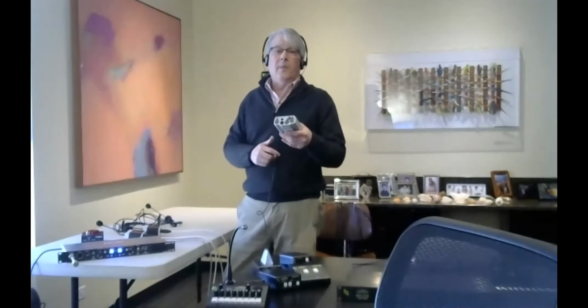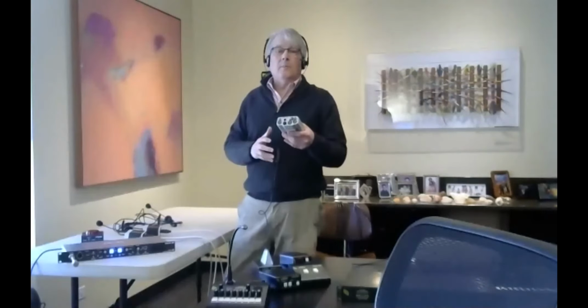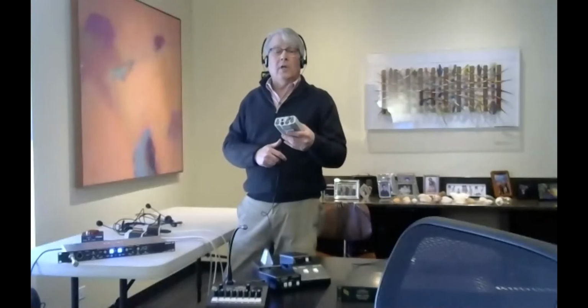TW system. And how do they do signaling? Probably like a call light. They probably maybe ran into a patent issue, but they use high frequency. So they use 20 kilohertz for call and 24 kilohertz as a mic kill signal. So that's really the background of analog.